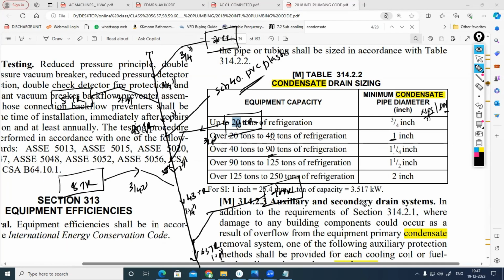In the chilled water session, I will explain the pipe schedule and nominal pipe size. Okay. Anyhow, the type of pipe material is Schedule 40 PVC plastic. Besides that, we are having different materials called CPVC, chlorinated polyvinyl chloride. We are having UPVC, unplasticized polyvinyl chloride. We are having PPR, polypropylene random. We are having HDPE, high density polyethylene. Then we are having ABS, acrylonitrile butadiene styrene. Different pipe material we are having.